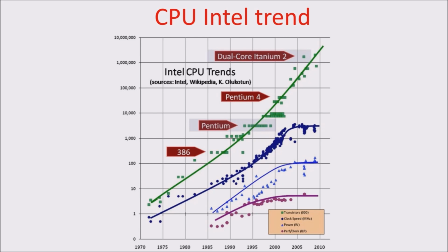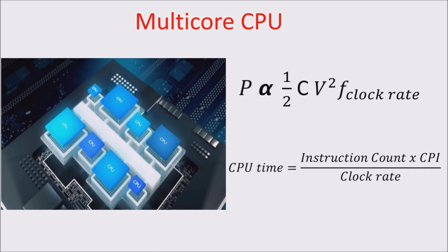All the improvements in these last decades have come from the parallelization. If we cannot improve the clock rate because of power consumption, we improve the throughput, so we improve the job done in the time unit, doing things in parallel. In this way, we increase the data processed without increasing the clock rate. For this reason, the multi-core CPU came in these last decades, where each core is like a little CPU. So that's where multi-core architecture comes from: the struggling battle between power consumption and performance.